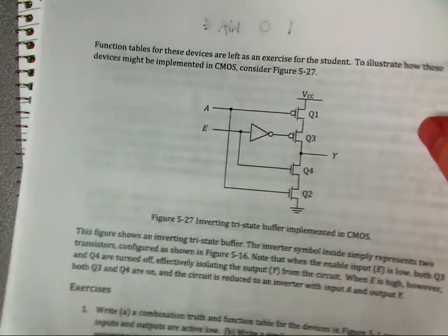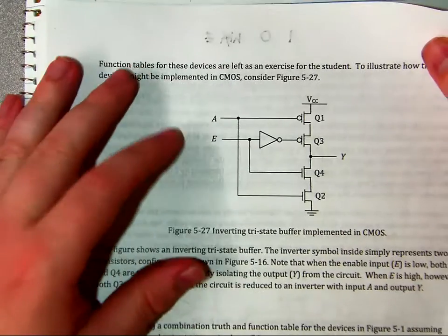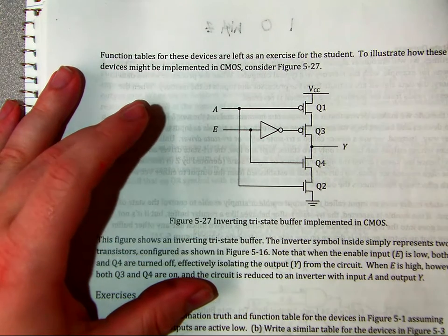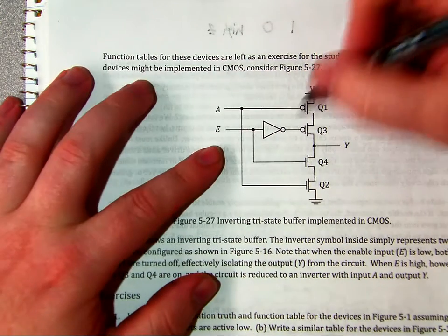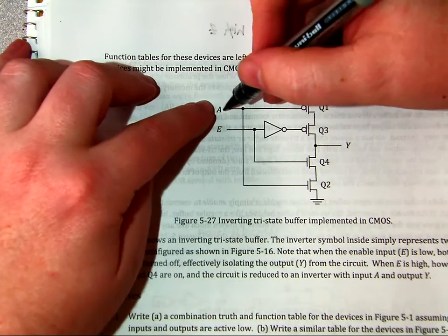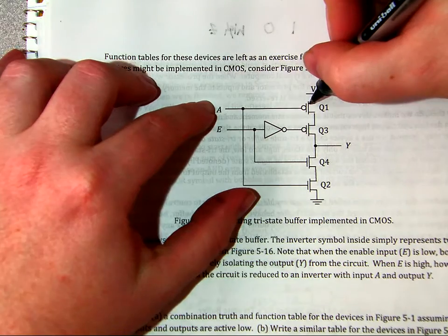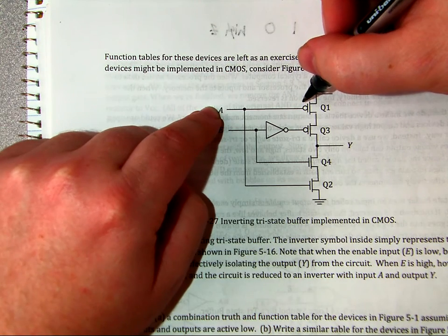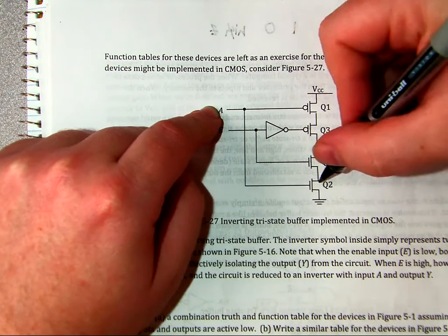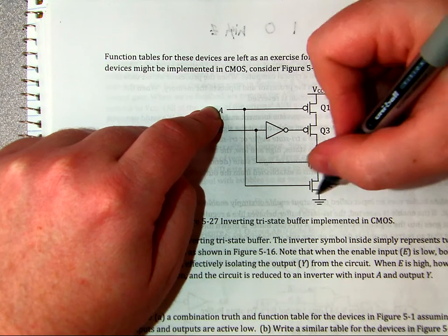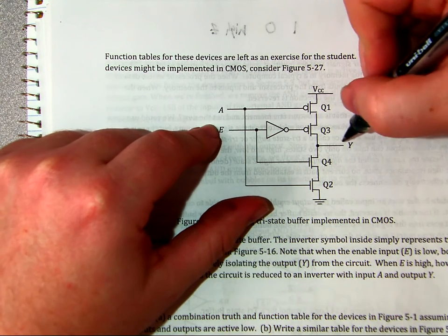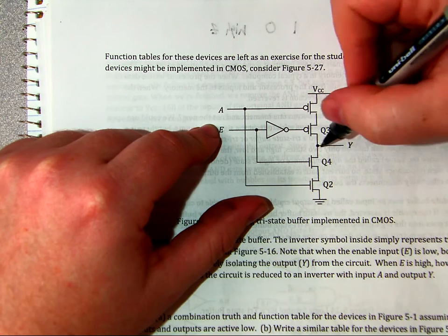What that means is, let's go look at the circuits, because we understand these circuits now. We understand that they're basically just switches. And this is a nice tri-state buffer, okay? It's going to be inverting because everything is inverting these days when we design in circuits, isn't it? So if I have an A as our main input, you'll notice that these outside are basically just the inverters. So if A is high, this guy is off, this guy is on, so we get ground. If it's low, this guy is off, this guy is on, so we get high. But the issue is Y can't see that unless enable allows it to.